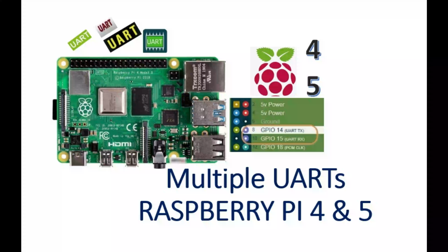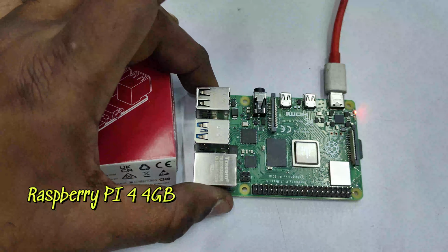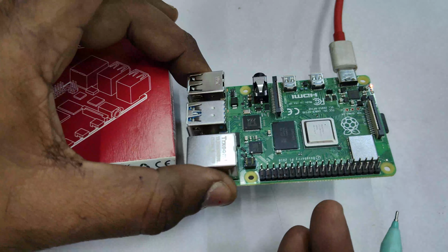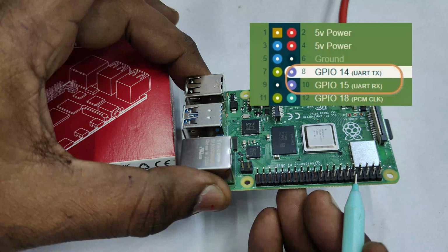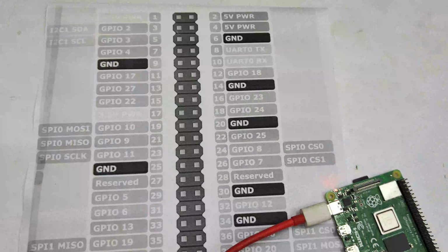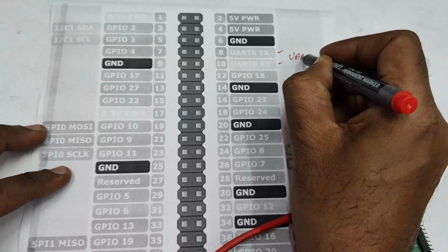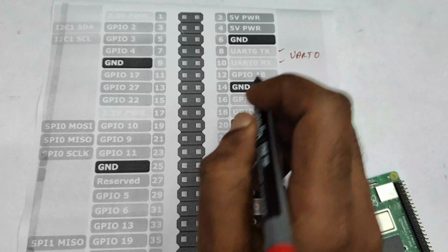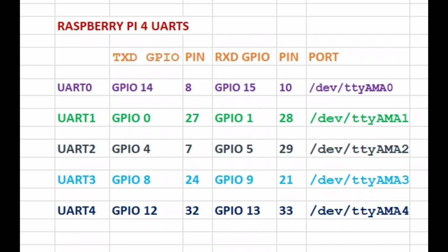Hello all, in this video we will see how to enable multiple UARTs on Raspberry Pi 4 and Raspberry Pi 5. Here we have Raspberry Pi 4 4GB, but this method applies as well to Raspberry Pi 5. The default GPIO 14 TX and GPIO 15 RX are for UART 0, and we have to enable this, and the other UARTs are UART 1 to UART 4. A total of 5 UARTs are possible in Raspberry Pi 4 and 5, UART 0 to UART 4.